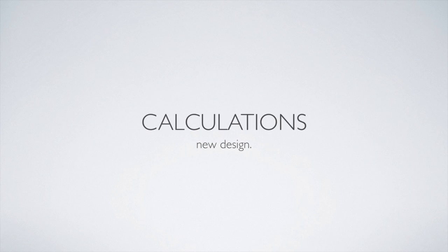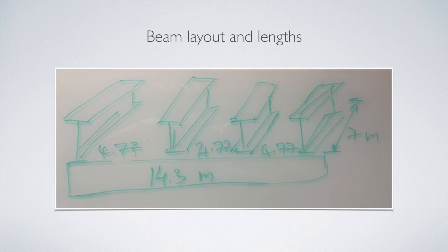Here are the calculations for the next design. To make up the total area required for this project of 200 square meters, each floor needed to be 100 square meters. So therefore we used the minimum length of 7 meters I-beams and 14.3 meters girders, with even spacing between.